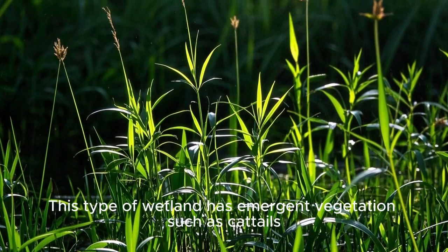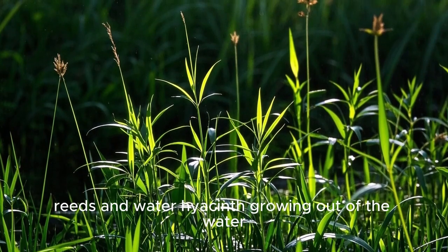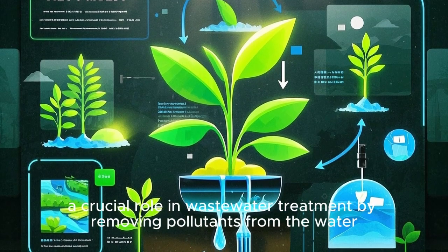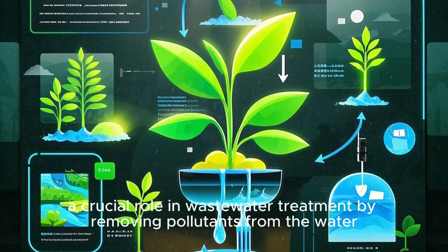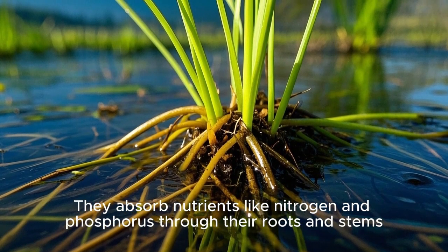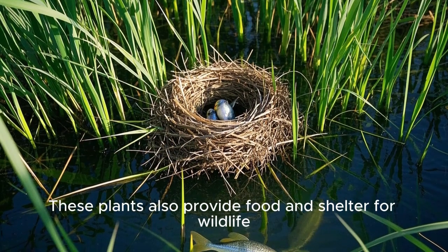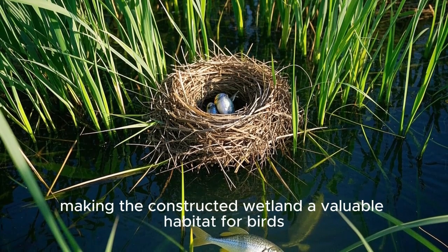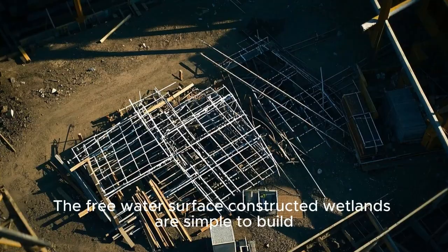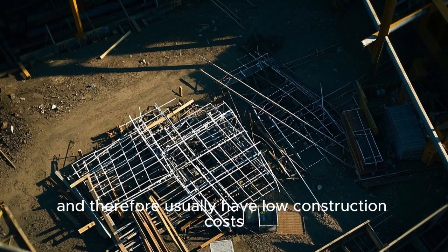This type of wetland has emergent vegetation such as cattails, reeds, and water hyacinth growing out of the water. These plants have special adaptations to survive in aquatic environments and play a crucial role in wastewater treatment by removing pollutants from the water. They absorb nutrients like nitrogen and phosphorus through their roots and stems, which helps to reduce eutrophication and improve water quality. These plants also provide food and shelter for wildlife, making the constructed wetland a valuable habitat for birds, fish, and other animals.